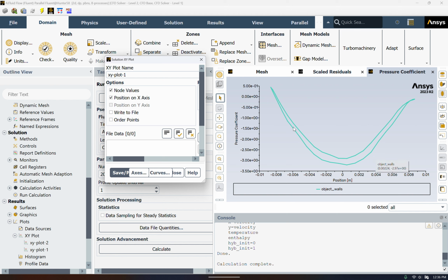And this should be about right. So we're within 1 and -3 for coefficient of pressure is what we're looking at. While we're not exactly at 1 for a stagnation point, that could be due to either a bad mesh or not having the best contraction ratio when we're referencing our velocity. But generally, like I said, you want it between 1 and -3, which it is. So this should be good. Thank you, and that's all for this part of Lab 3.